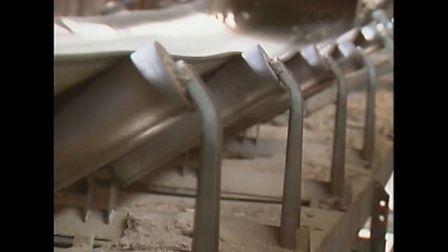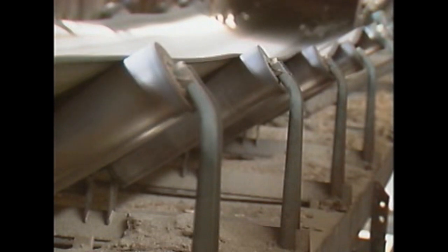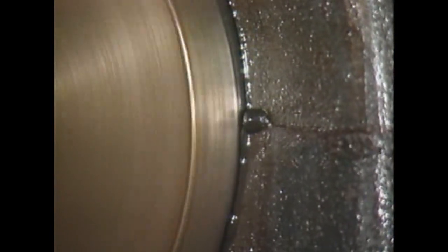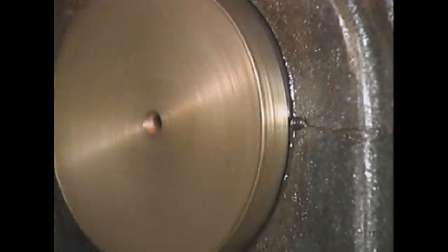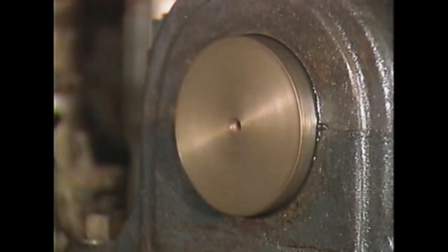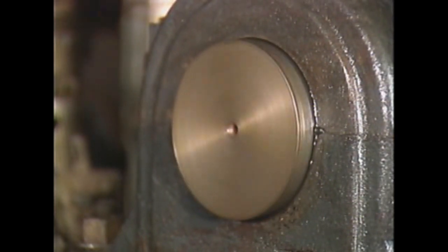There are various reasons for using grease, most of which depend on the operating conditions in a given situation. Under certain conditions, grease may be necessary to ensure that the lubricant will stay in place. As long as grease remains semi-solid, it tends to stay where it's put. Oil is much more likely to flow away from where it's needed than grease is. Even when both oil and grease would flow out of an area, it's much easier to retain grease with a seal than it is to retain oil. Keeping the lubricant in place is important because leaking lubricant could contaminate surrounding areas or cause a fire hazard.